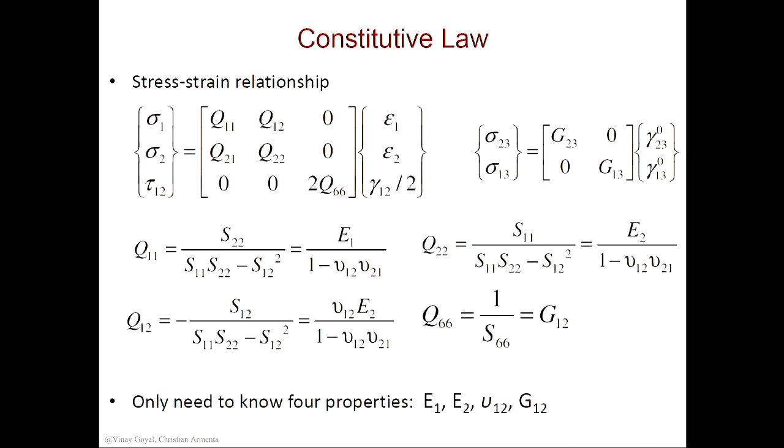So now all these properties can be measured, and if you know all these properties, you can get these Qs, okay? These Qs, and the formulas are given here and how to calculate the Qs. So the first question I want to ask you is, do you agree that I can get these Qs? Yeah? So if I know E11, I know the Poisson ratios, I gave you the formulas for Q, didn't I? So those Qs fully populate my matrix Q there.